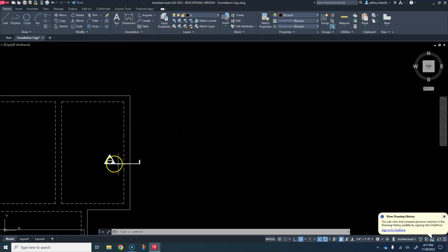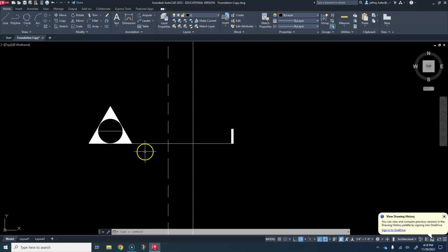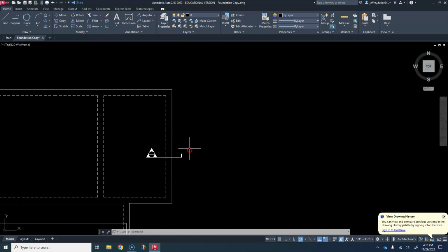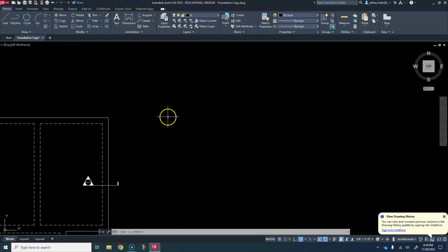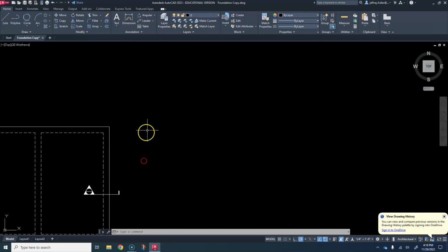This symbol here indicates that there is a cutaway here in another drawing that represents this view from the side. In this symbol, you would know how to find that drawing in a set of plans, because right here would be a page number on the top of the circle and then a drawing number down at the bottom of the circle. That would direct you to exactly where to find this in the set of plans. But we're not worried about that right now because we are not working with a set of plans, but that is just part of learning how to draw one.